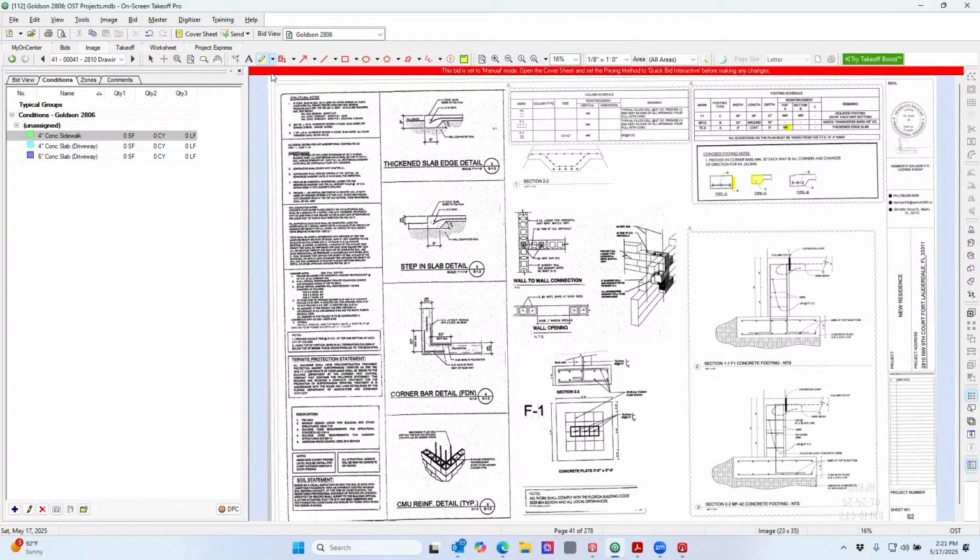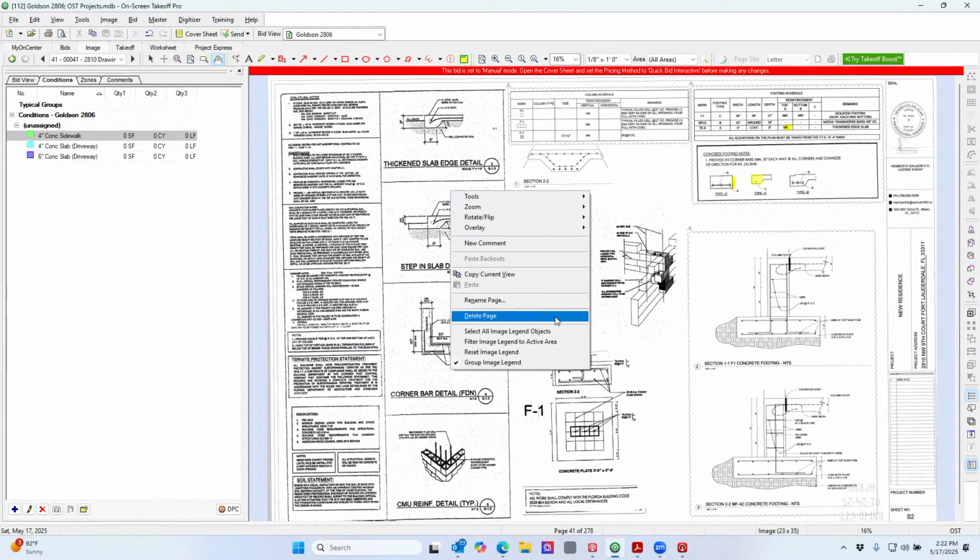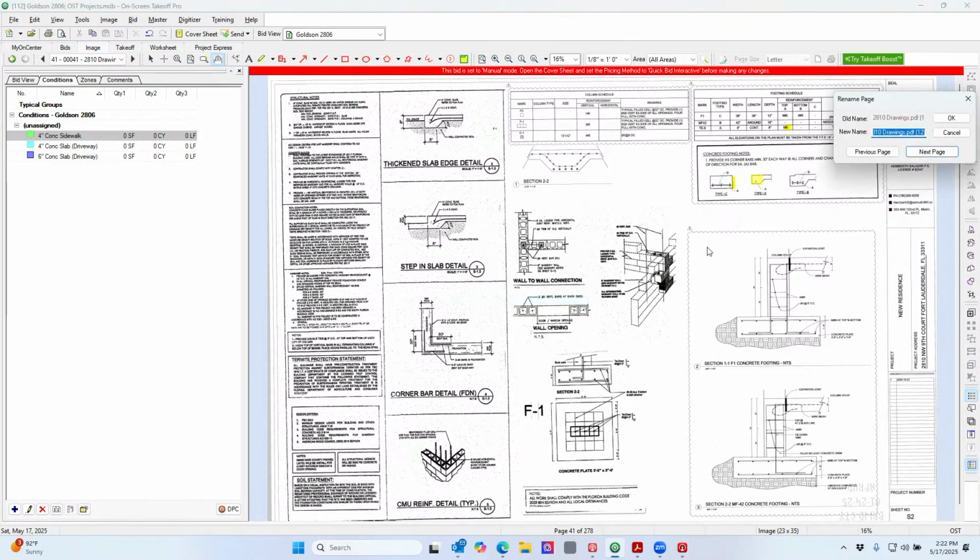This is slightly off topic, but since you mentioned trusses, how would you take off trusses? So I just take them off by square foot. Some people, if you are an installer, you may have to figure how many pieces of trusses you have, because you may figure out your production by how many trusses you can set in an hour. You follow what I'm saying? But if you're not installing it, then I would just take them off by square foot. Did that answer your question? Yeah.